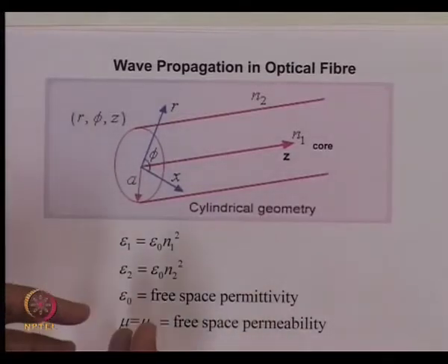So, we ask, if we consider the electromagnetic wave which is source free, in what form would this electromagnetic wave exist inside this cylindrical rod, which is a dielectric rod surrounded by a dielectric material. This structure essentially is a dielectric waveguide. So, we are asking, if we consider a source free situation, what kind of electric and magnetic field distributions would survive inside this dielectric waveguide.